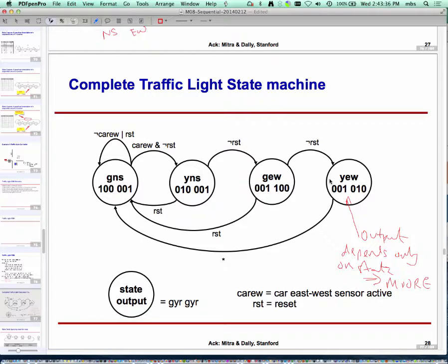So that tiny one clock cycle delay of a few microseconds at best, perhaps not even that, is minuscule relative to the system you are designing. Because we are making a Moore machine, the output will only be affected after a clock cycle delay, but our clock cycle is so much faster than the speed at which cars are moving that it is inconsequential. In some other systems that may be an issue.